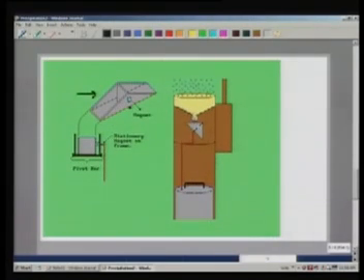One of the compartments is below the funnel, so it collects all the water, and when a fixed amount of water has entered into this bucket, it tips over. So then it rotates and the other compartment comes below the funnel, and then it will start collecting. And when it tips, there is a magnet here which will send a signal to some recording device, and we will know how much time it took to fill one side of the bucket, and we know how much rainfall has been collected in that time. So that way it records these tips which tell us what is the intensity of rainfall.